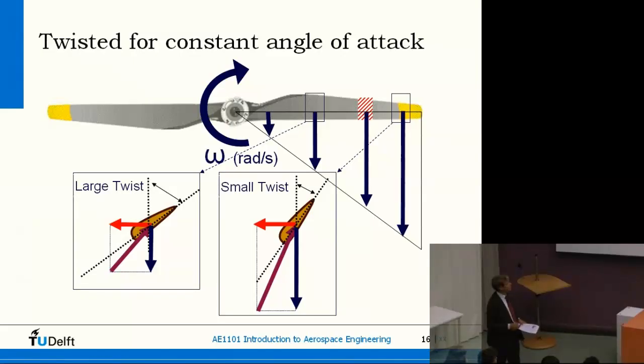So if you want to do this right, if you have a fixed propeller, that would only work right for one airspeed. And that's why you want to twist the propeller to compensate for airspeed or rotational speed to make sure that the angle stays right. So that's why we have variable pitch. It covers changes in rotational speed and in airspeed, and avoids the problem that a fixed propeller is only optimized for one condition, one ratio of airspeed and propeller speed.